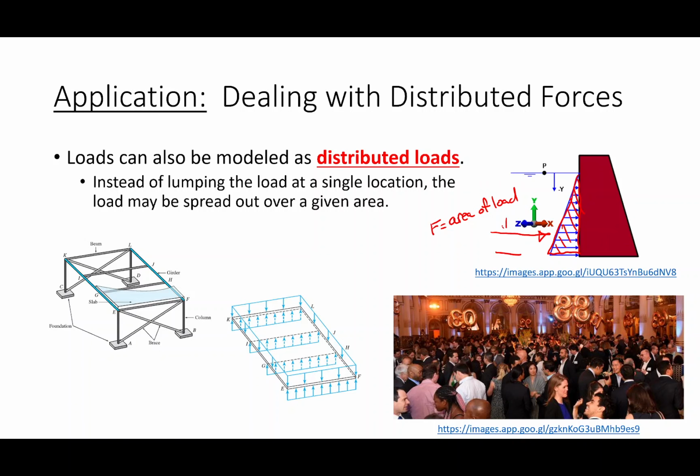Now, where do you think I would place it? What would this distance be? It'd be the centroid. It'd be y up. Does that make sense? So you would place this vector at the centroid up. Why am I placing it there? Because if I place a vector here that has the same area and place it at the centroid up, I propose it has the same static equivalence as the distributed load. And the beauty of that is I know how to solve for reactions and analyze structures for this because we've been doing it all semester.